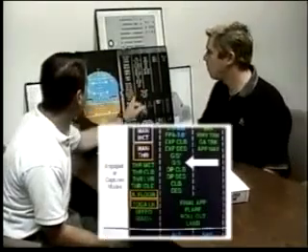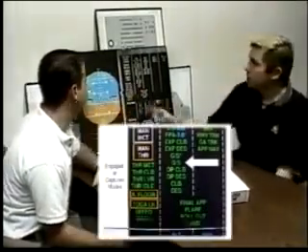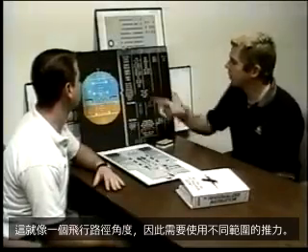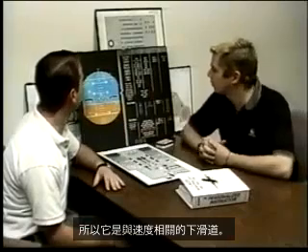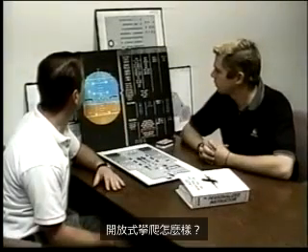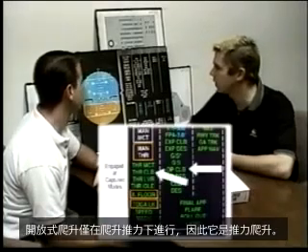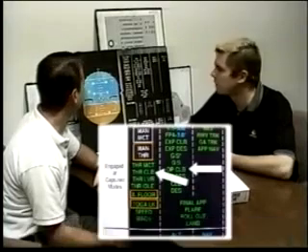Glide slope's engaged. What mode would you get in the auto throttle column? It'd be speed. It's just like a flight path angle, so it needs to use a varying range of thrust, so glide slope is associated with speed. About open climb: thrust climb, open climb. Open climb is only done at climb thrust, so it's thrust climb.